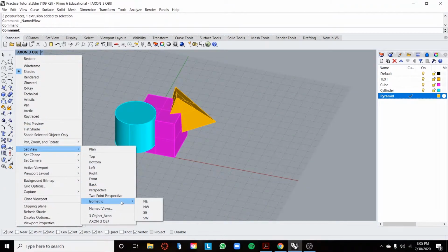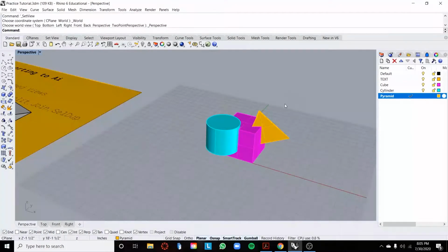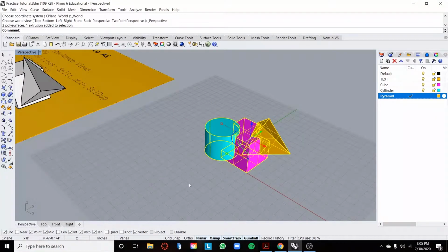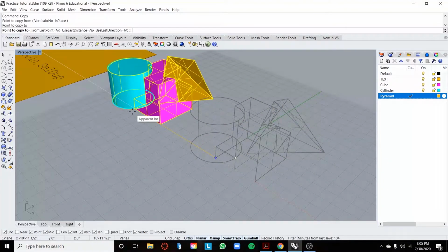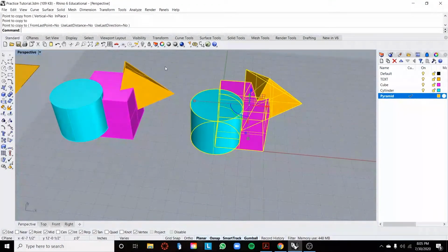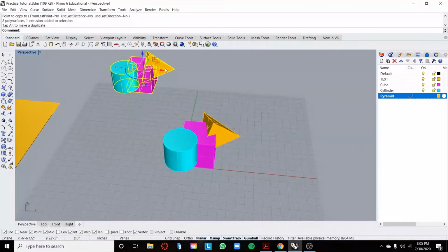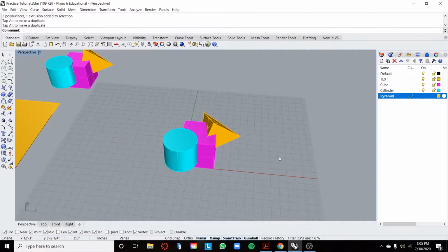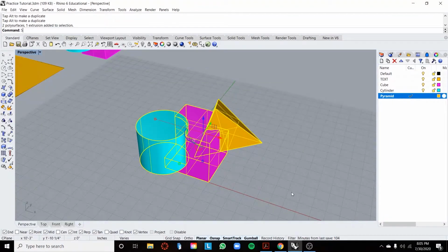So before we use the make 2D command, we want to scale down this cluster of objects. And so let's first make a copy. It's always a good idea to keep an unscaled copy of your model. We'll select this cluster again, type in scale into the command line. It's prompting us to pick a base point. I'll pick the origin point.